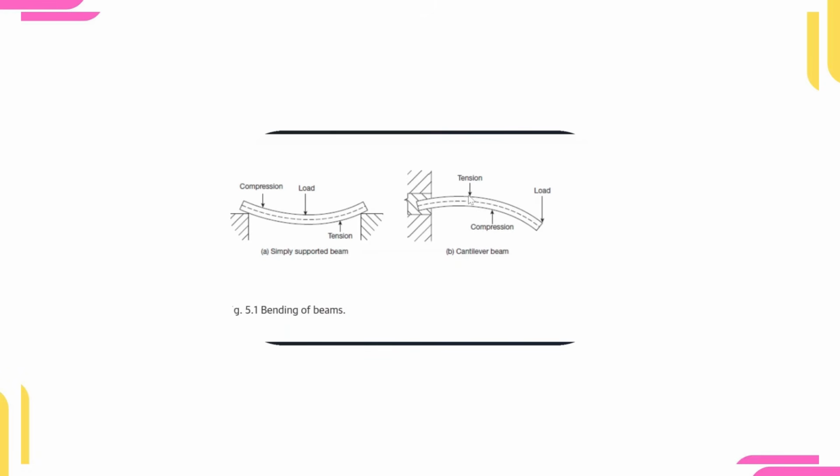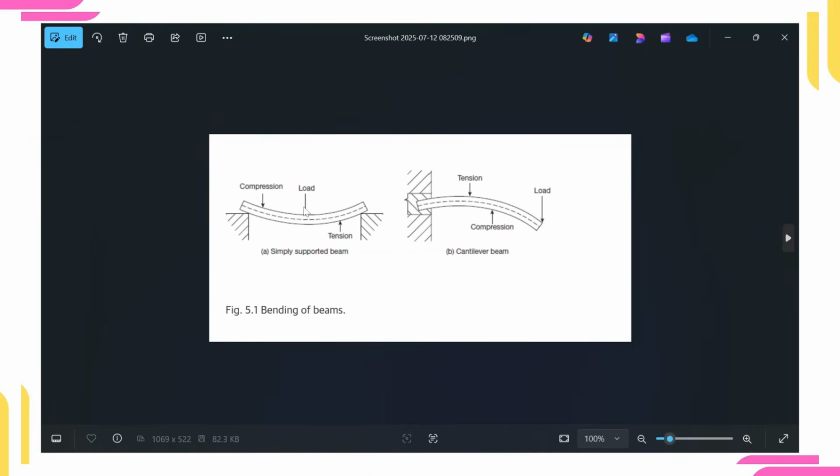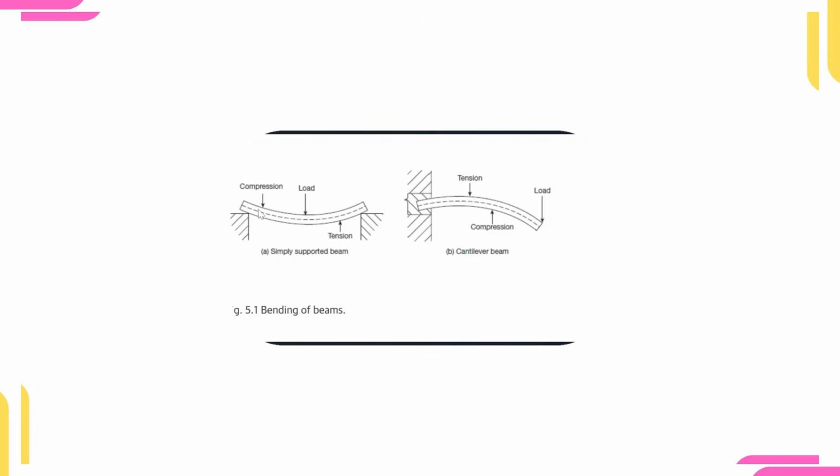So in other words, to counter this, in cantilevers we provide reinforcement at the top portion, while in beams we provide reinforcement at the bottom portion, but that is only applicable to simply supported beams. In continuous beams, the support parts are subjected to tension, but we'll explain that later. I just want you to understand that in a cantilever, the top part is the one subjected to tension, and in a simply supported beam, the bottom part is the one subjected to tension. And two, concrete is very weak in tension. That is why we always reinforce the tension zones.